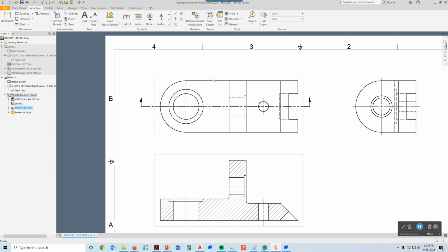So let's just focus on the top view first, since that was our principal view. I'm going to put a dimension in from this corner here at the top to the center of that hole, and I'm going to move outside my cutting plane line and place a 1.5 like that. I'm going to use a hole and thread note because that's how I created this counter bore. And I'm going to pick right there. I'm going to move this guy right up into here and pick. I can fine tune it later if I need to.